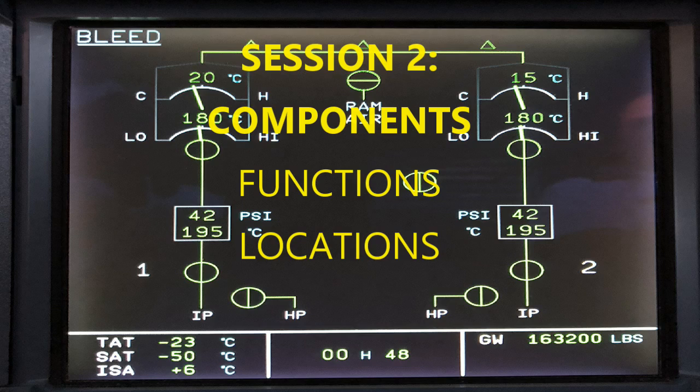So at 257 degrees Celsius, that's when the pressure regulating valve is going to close. It also closes if there's an overpressure downstream of the pressure regulating valve, and that overpressure is at, give or take, 57 psig.